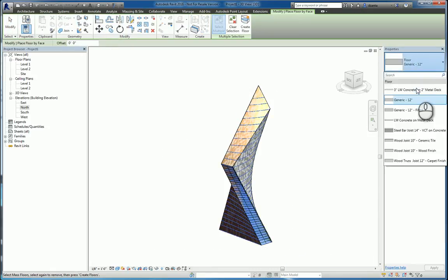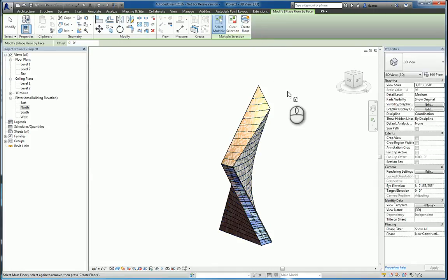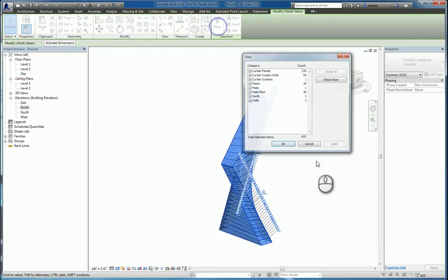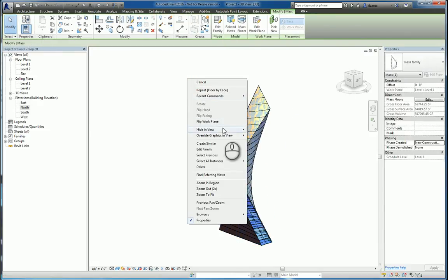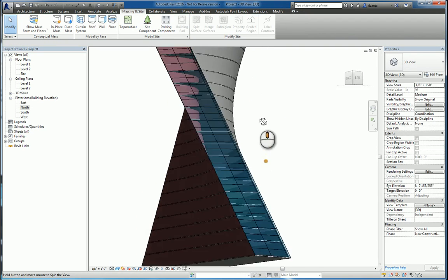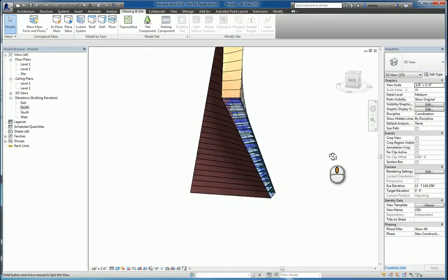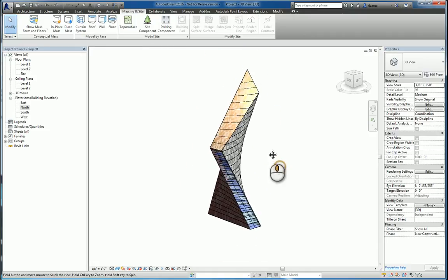And what kind of floor are we working with? Pick the one you want or make your own. Click Create Floor and it will get created. You want to hide that mass object. Again, you can just select everything, check the mass object, right click, and hide. And so very, very quickly I can use the Building Maker tools to build a Revit model based upon that mass object. I'm going to undo the visibility of that mass object.